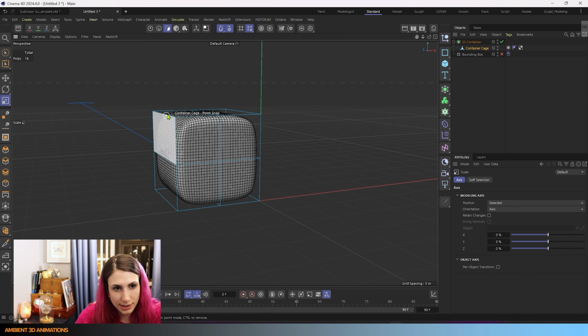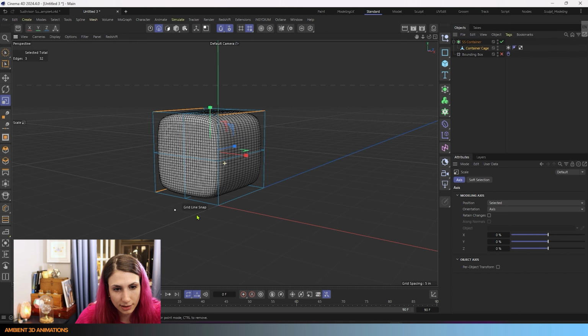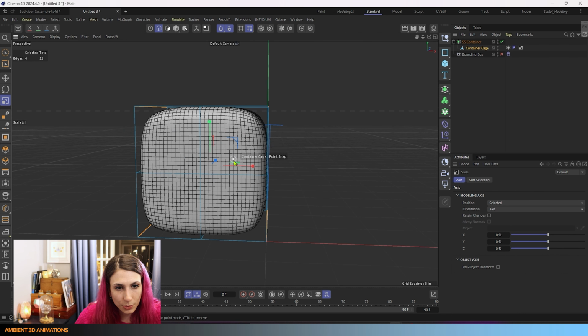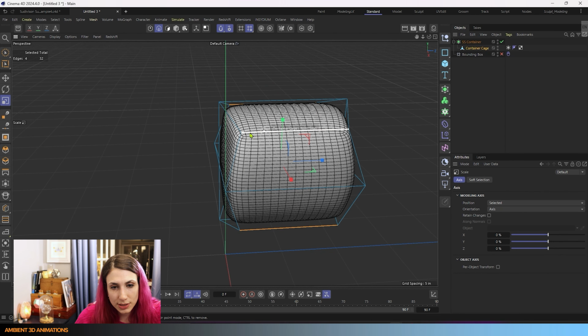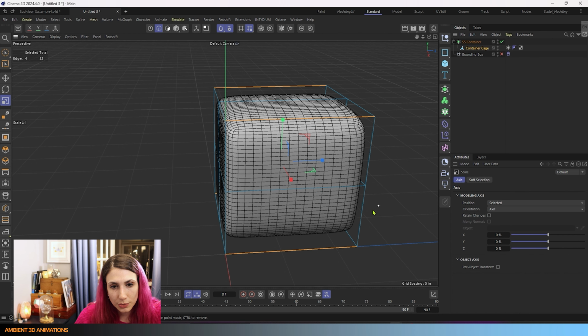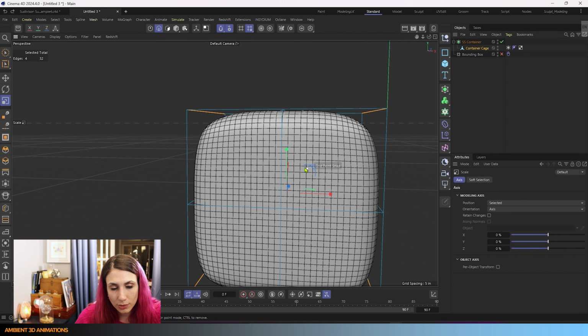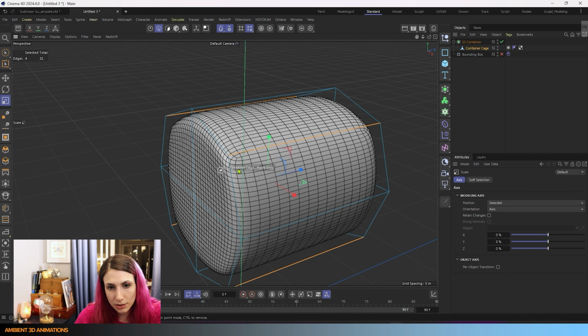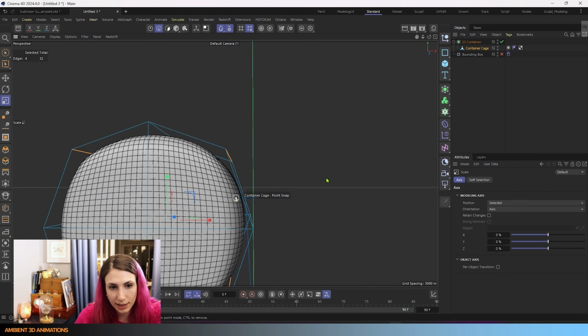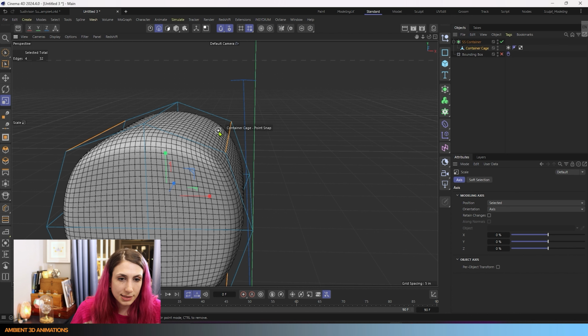So I'm actually going to hit undo a couple times, and I'm going to go back into our edge selection we had before, and I'm going to scale these in a little bit differently. So we used the T hotkey before, and we just scaled in like this, but this is also scaling it within the Z. And what if I just want to scale it around this here, where the Y and the X, but not the Z? Then I can click on this here, and I can scale that in so that those edges stay nice and neat and aligned so that we keep that the same.